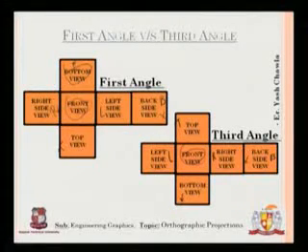The view which is upstairs in first angle comes down, and vice versa, and which is left and right, they also interchange when we go from first angle to third angle. So it is very necessary that you should mention in the solution which angle you are drawing this solution in, or else if it is mentioned in